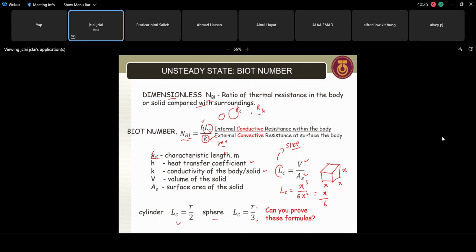Then the Biot number will be bigger for the 1 meter diameter copper ball. Then it has a high chance that the Biot number can be greater than 0.1. Then we cannot assume the whole copper ball has uniform temperature distribution across the ball.